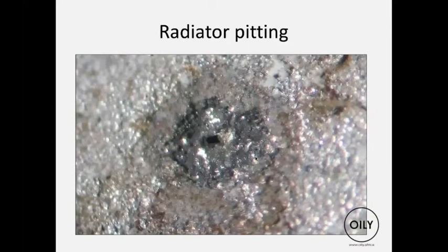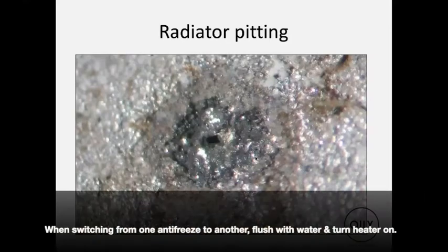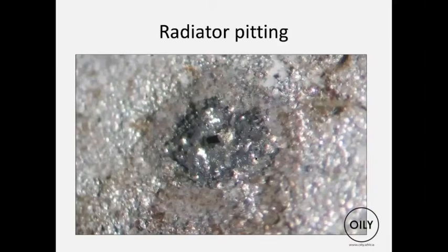And that's off a big Hino truck. Genuine Hino radiator, 2 weeks, holes through it. So when you switch from one antifreeze to the other, flush with water and turn the heater on to drain antifreeze out of the heater as well, and then you flush the whole system. You fill it with water, leave the heater on, start the engine, circulate, drain it, do it again, and then put the new one in.